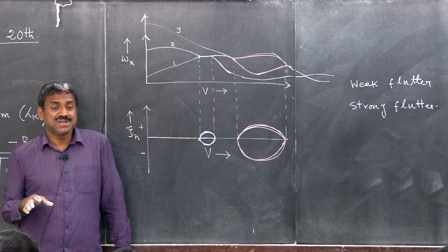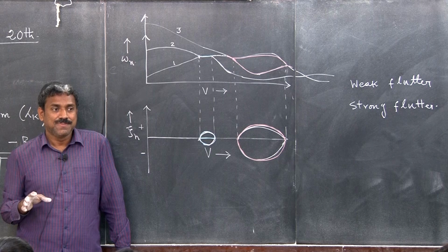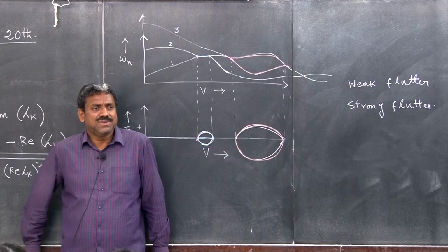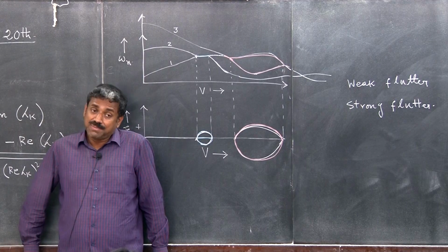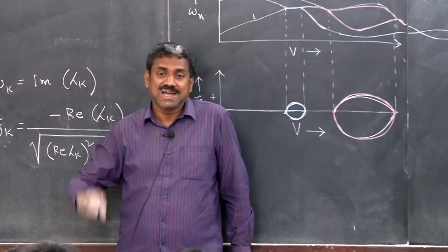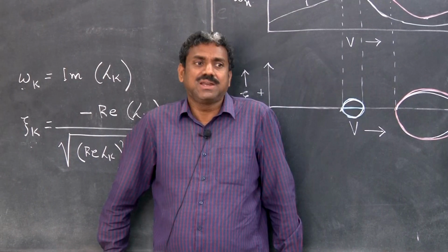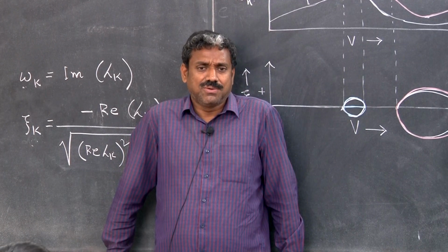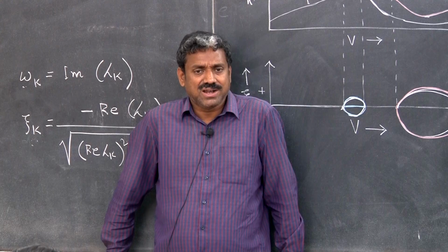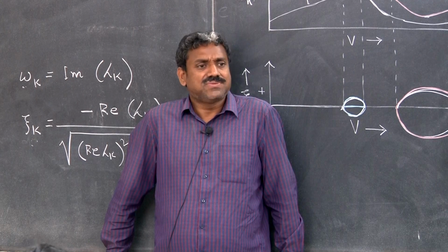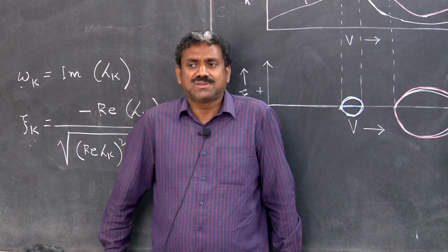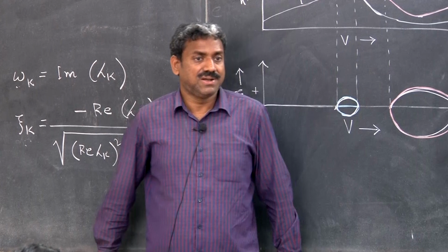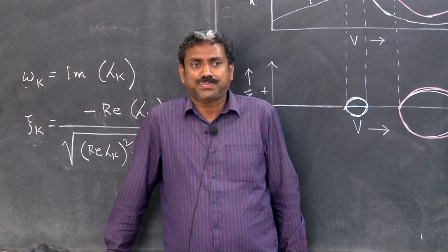Cable suspension or cable stayed are flexible enough to have flutter, but what about girder bridges and others? There flutter generally does not manifest as a global failure mode. There might be localized flutter of some component, that is a different thing, okay. That is why you will see steel bridges, steel girder bridges etc., are not checked against flutter. Wind tunnel tests are mandatory to conduct for the cable stayed and cable suspension bridges, which have a larger span, and because of the suspension cable and the load resisting system, they are inherently flexible. That is what is done, okay.